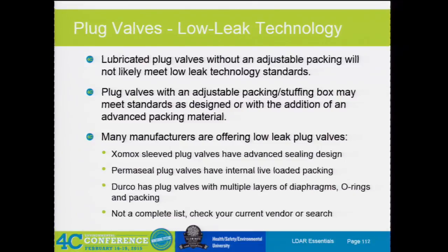Lubricated plug valves without an adjustable packing will not likely meet the low leak technology standards. So plug valves with an adjustable stuffing box may meet the standards as designed or with the addition of an advanced packing material. And manufacturers are offering low leak plug valves though. And there's some of those manufacturers.